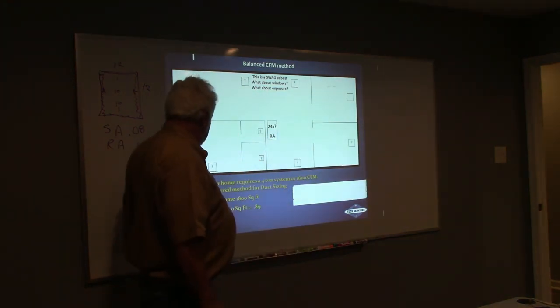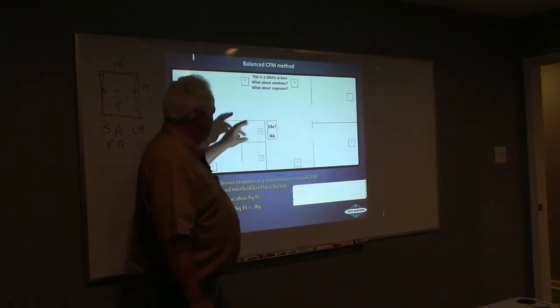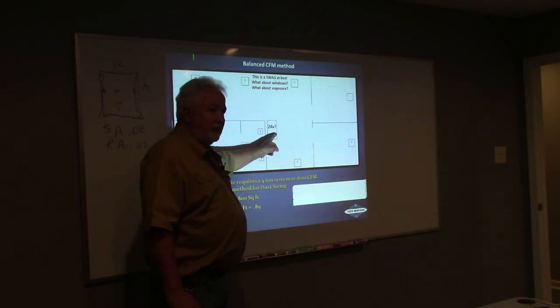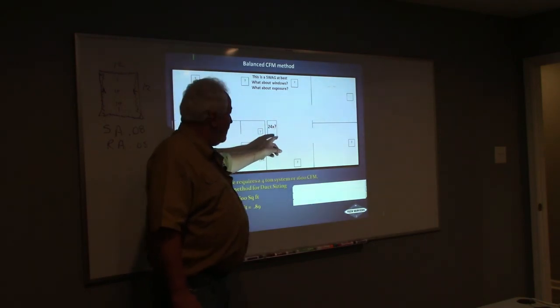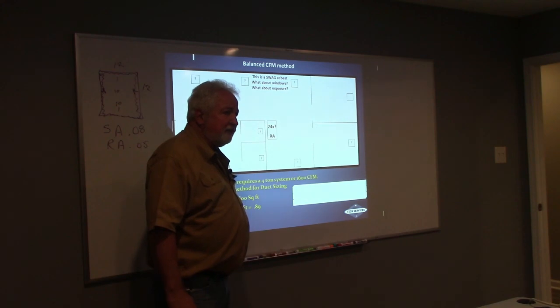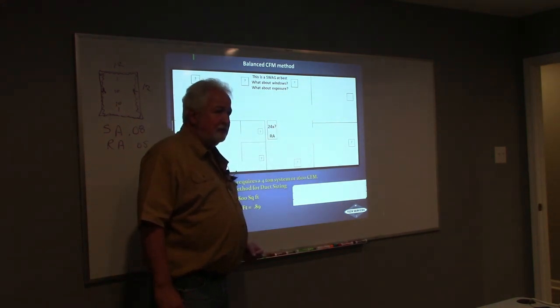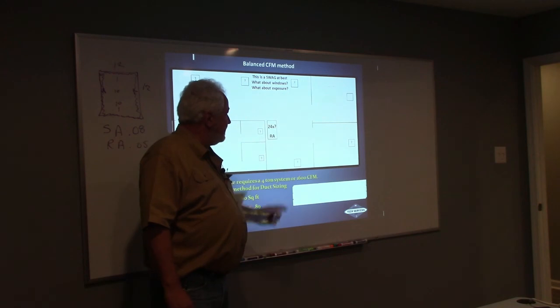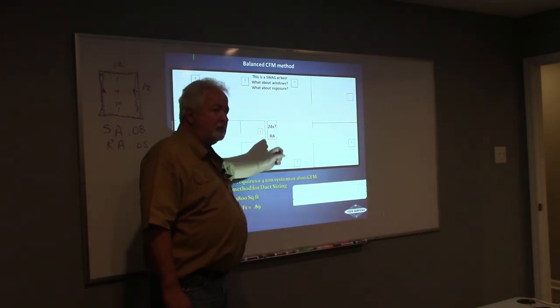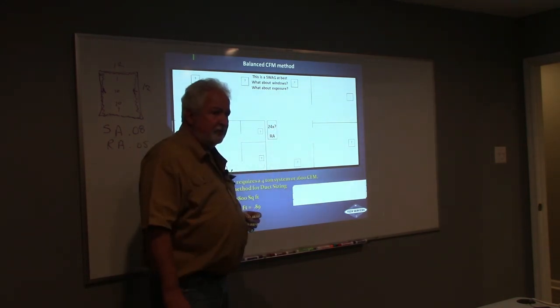I've got a 4-ton system. I need a 24 by something return air grill. What do I need to have in order to get 4 tons of air through a 24 by something return air grill? Height times width times 2, is that right? So pick a number. 30. 24 by 30, do it. 24 by 30 times 2. 1440. Is that enough for 4 tons of air?